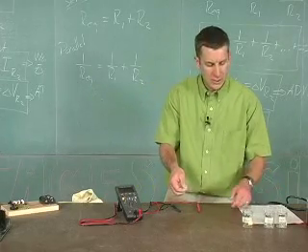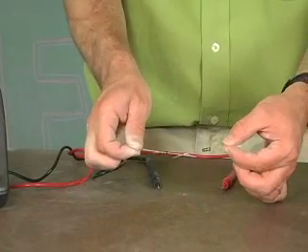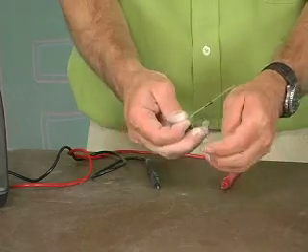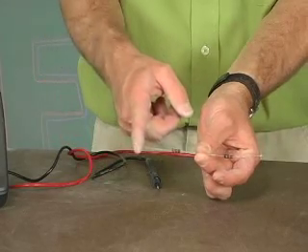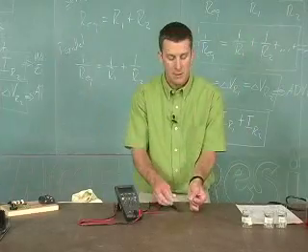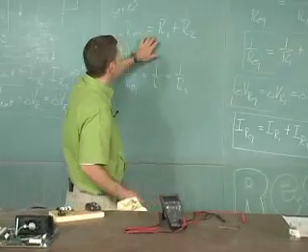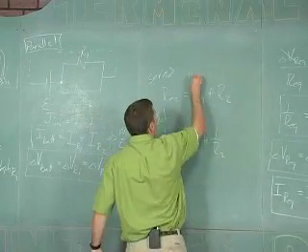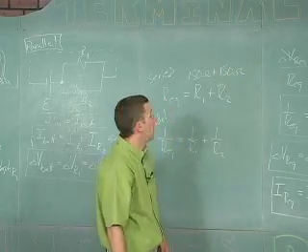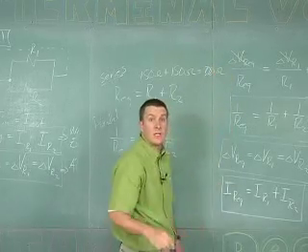Now, as we look at two resistors in series, you can see that to hook them in series would literally be to touch them side to side so that both ends are touching. In this way, you can see that the current that flows in this side must go through this resistor, through the wires, and through this resistor to get to the other end. Now, according to our mathematical expression here, if I was to look at two resistors in series, I would have 150 ohms plus 150 ohms. Well, 150 ohms plus 150 gives us a value of 300 ohms when hooked in series.